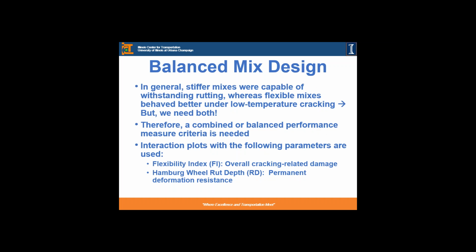With that information, we also wanted to put this into perspective for mix designers, combining this with rut resistance, so a balanced mix design approach. We really generated stiffer mixes. They were working very well for us to eliminate rutting problems, but we want these mixes to do both. While you're eliminating the rutting problem, we also want the mix to perform against cracking. So that's why we came up with this combined balanced performance criteria, achieved by plotting the flexibility index with rut depth and then assigning some zones to stay away from.